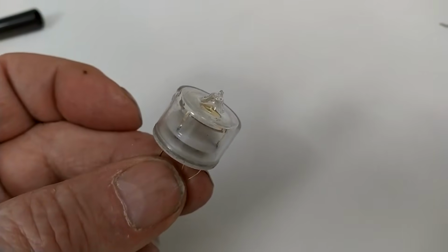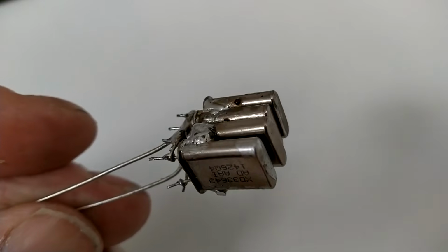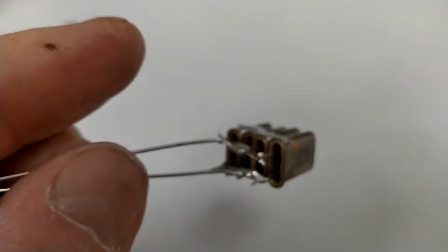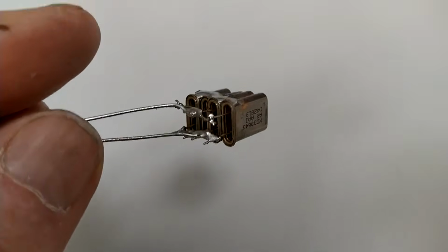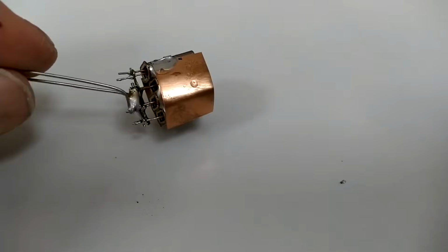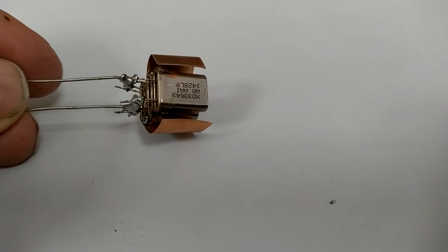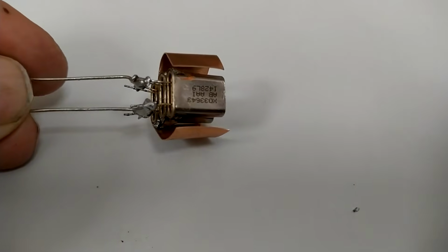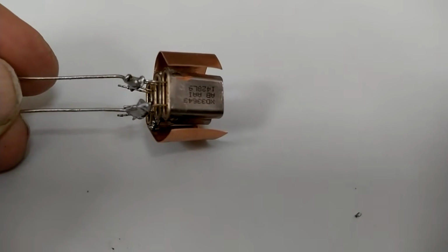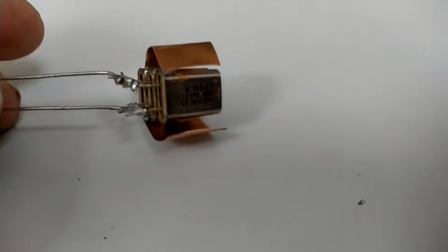The old crystal is one of these from Bell Labs. I will replace it with this group of 4 parallel crystals. It will fit into the same oven. Some copper will provide mechanical stability and make this unit fit into the hole that previously held the old crystal. So good heat contact with the oven and mechanical stability should be provided by the copper.